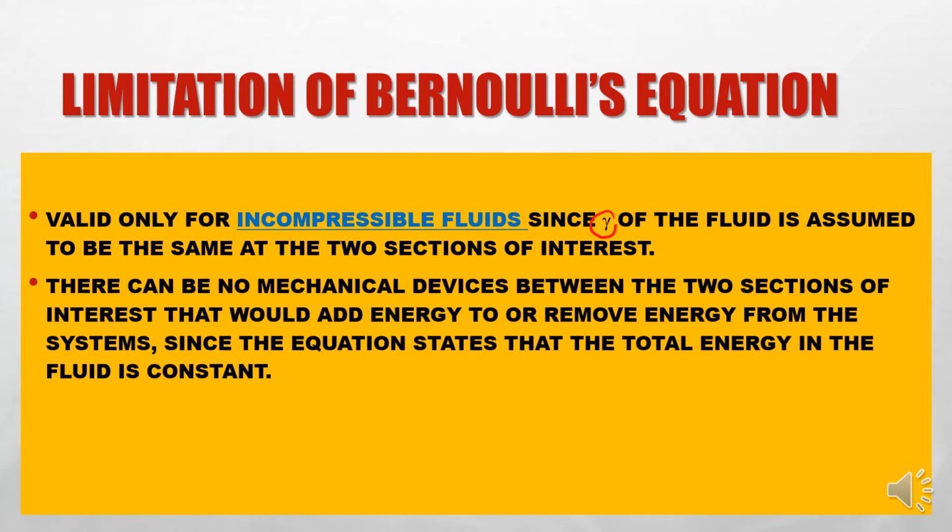The second limitation is that it cannot have any mechanical devices between 2 points. For example, if you want to use Bernoulli's equation between point 1 and point 2, you cannot use any mechanical devices such as a pump or compressor, which can remove or add energy in a system.